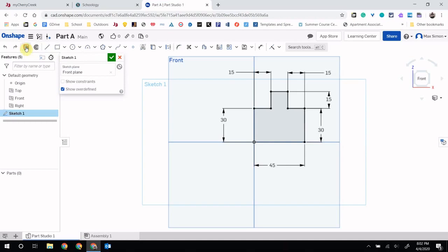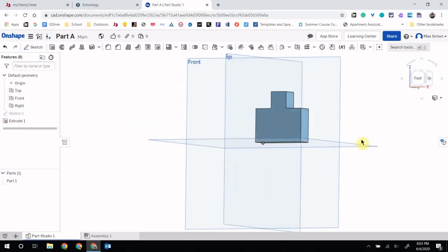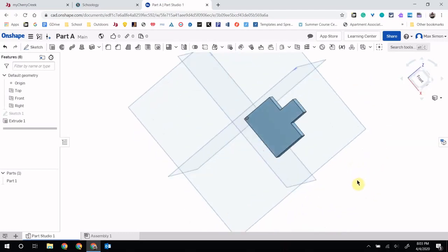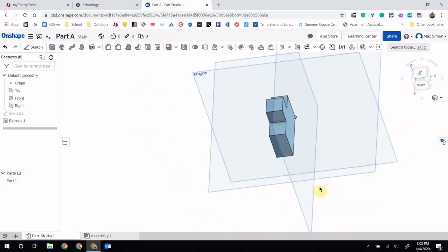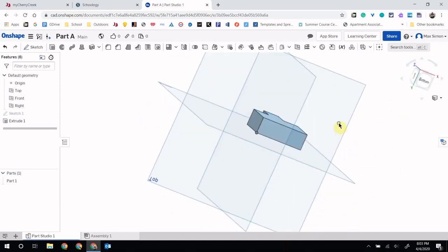We're going to extrude this now. And we're going to extrude it to a depth of 15. And when I say depth, that means a distance. We're extruding that out to 15 millimeters as well. And we're making a new surface or new product. Okay, so when we accept that sketch, now, right, we have drawn that out to 15. So we have our basic shape here. All right, so now we are just going to keep building on top of that.